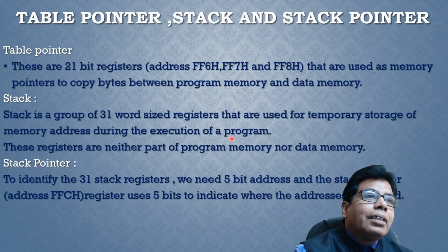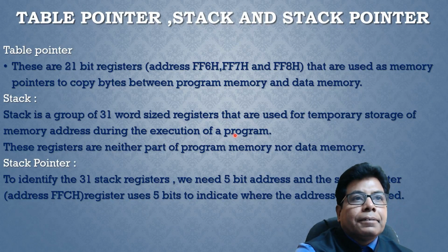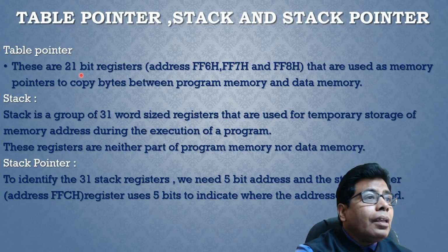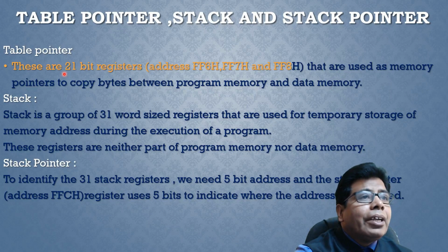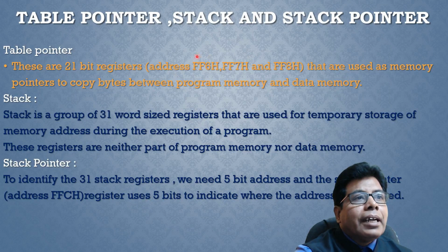Then the table pointer, stack pointer and stack. Now the table pointer is a 21-bit register. The addresses here are FF6H, FF7H and FF8H, and they are used as memory pointers to copy bytes between program memory and data memory.